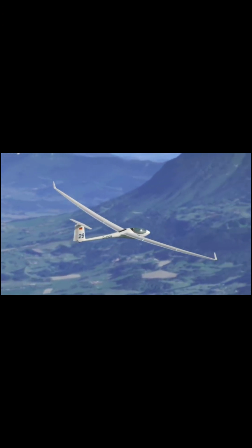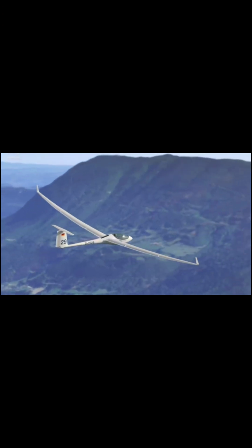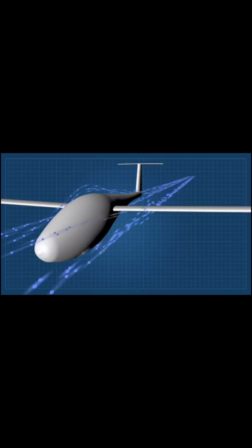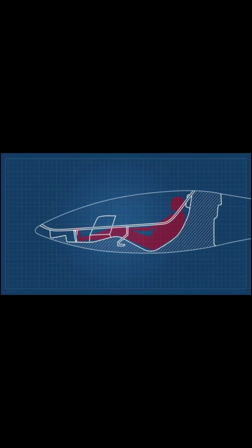The thin wings generate less aerodynamic drag than the common wings that are seen in self-propelled airplanes. In this way, the glider can pass through the air with less difficulty, obtaining the same lift and losing less speed than other airplanes. Another factor that helps for better aerodynamics is the design of the fuselage, making everything as smooth, thin and aerodynamic as possible, which is why the pilot enters the cockpit in much the same way as a Formula 1 driver in his car, almost lying down.